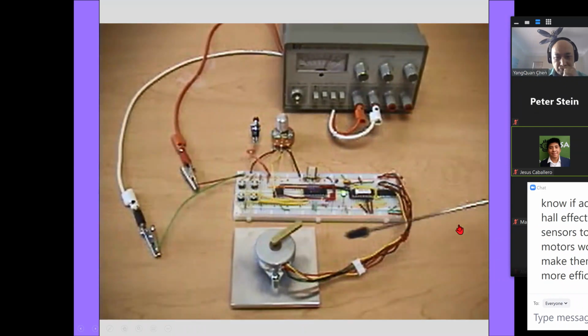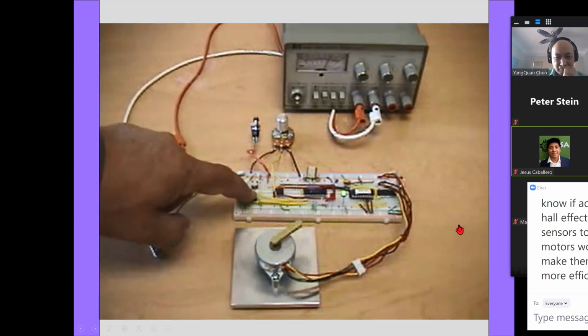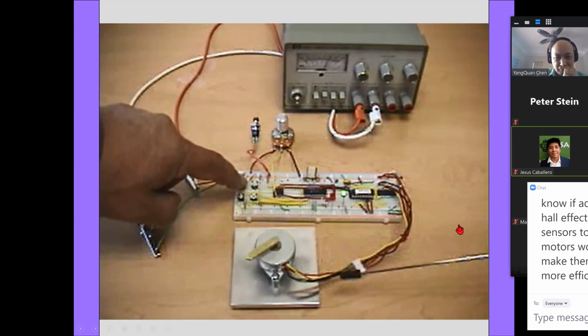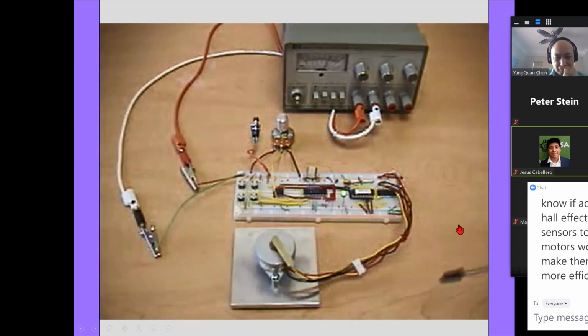So there we move from the 45-degree position and back to the 0-degree position. That's the fourth button, which moves to the 180-degree position. And you can see the motor taking one step at a time. This particular motor has 7.5 degrees per step.